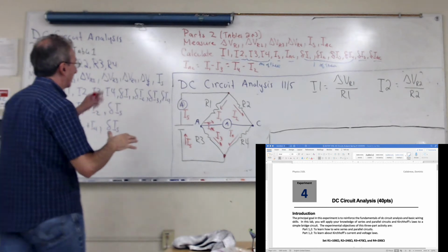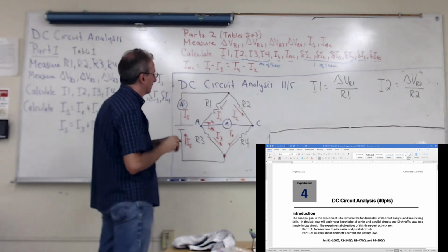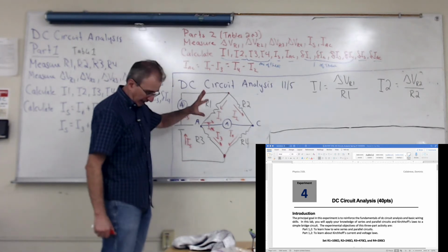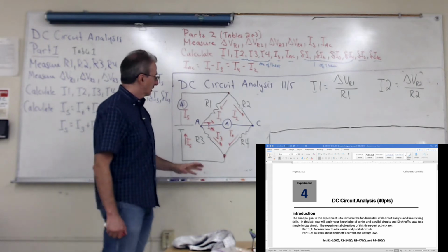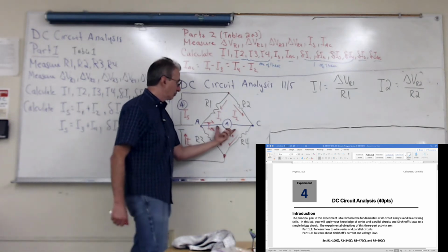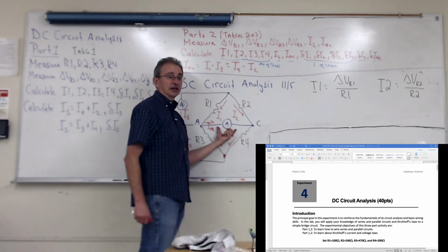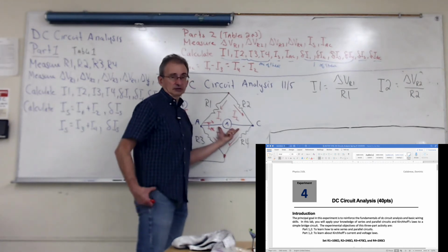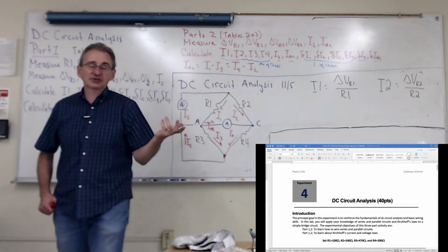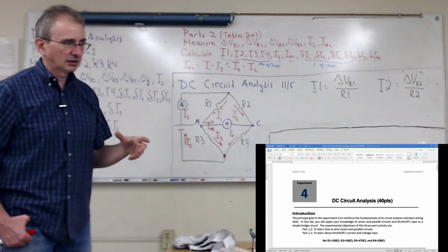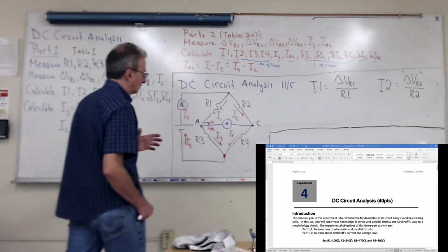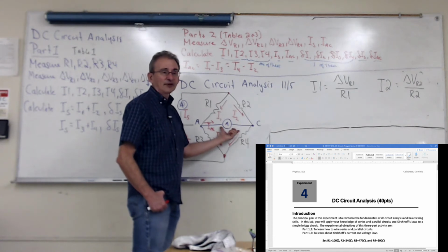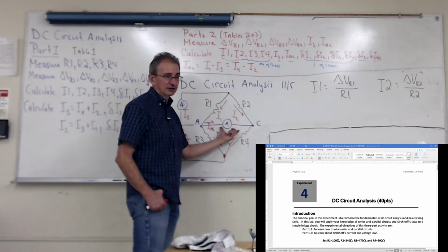So we've talked about calculating I_AC and I sub s for this part, but you're going to do this part twice, and I'm not going to have you do all the calculations the second time. The reason I want you to do it twice is I want you to change the current setting on the meter. The first time, you want the meter on the highest current setting, so it has the lowest resistance. That'll be the 10 amp scale. I try to choose the resistor value so even on the 10 amp scale, you'll get a reading. If not, just go to the next highest.